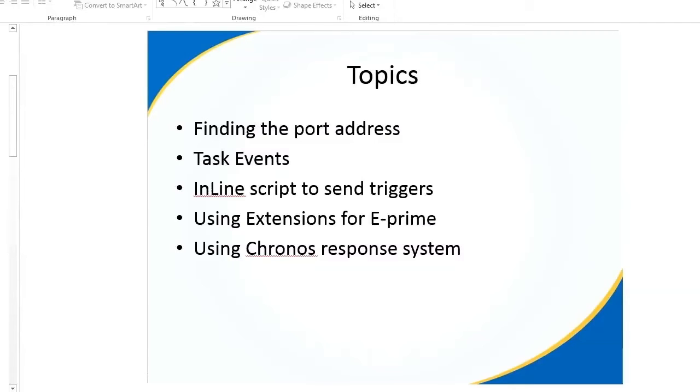In ePrime 2.0, port communication allows you to interface with an external device that connects to your parallel port, socket device, or serial port. As I mentioned, the signal can be sent before the object, following the object, or even at the onset of an object. While ePrime is capable of sending a signal to the port for interfacing with the device, the actual receipt and handling of the signal by the other device that you're interfacing with is the responsibility of the user.